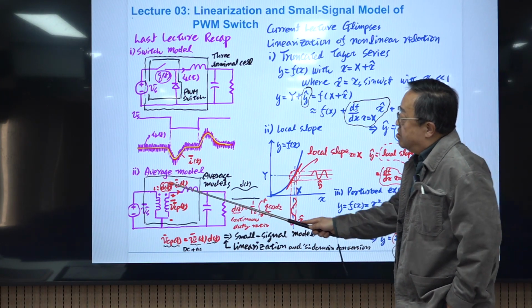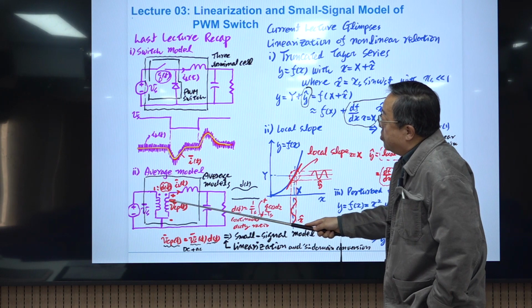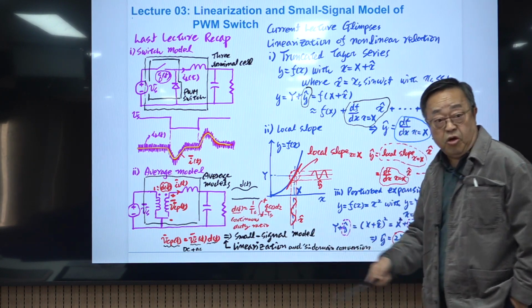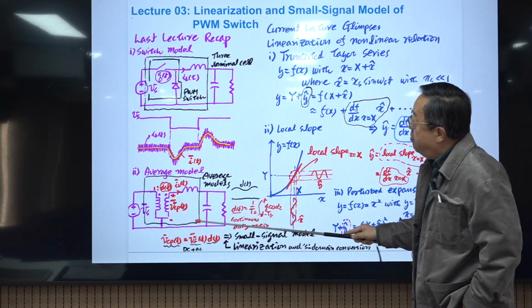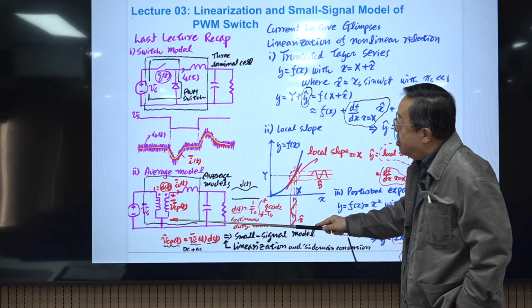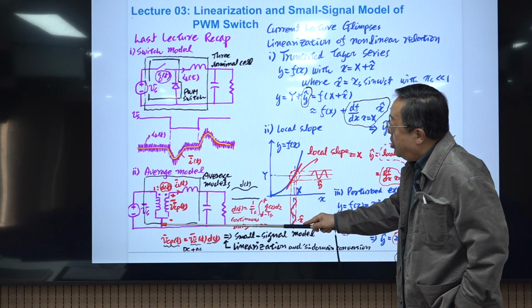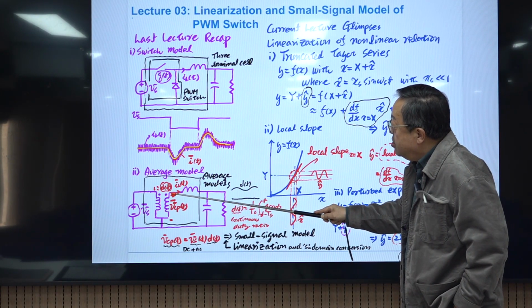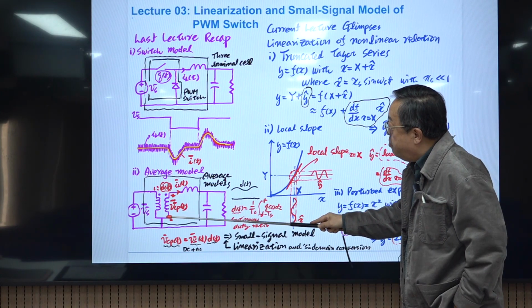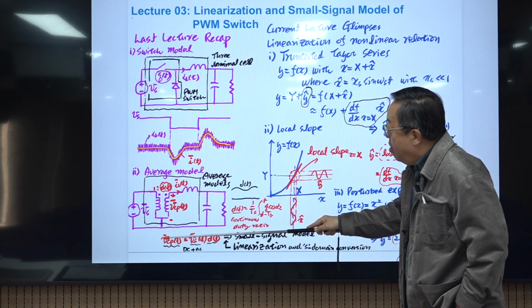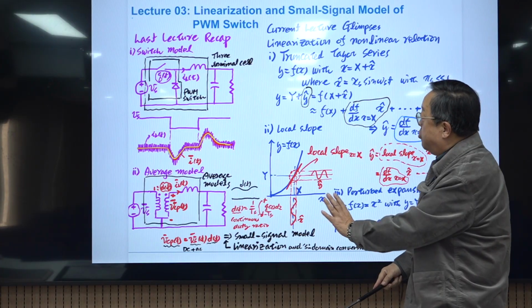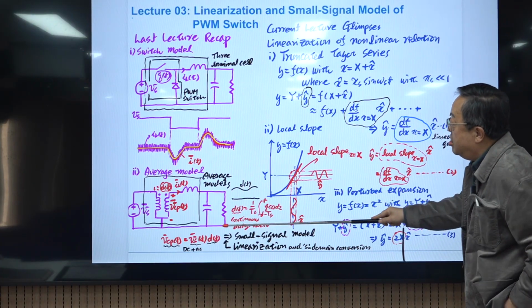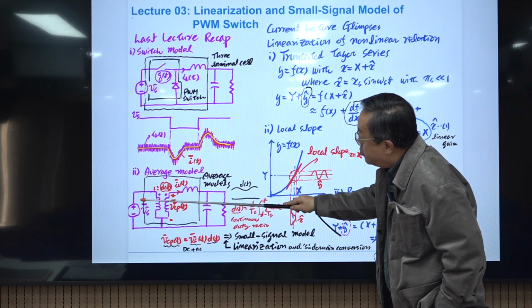So this is time invariant, but it is a nonlinear circuit model, because, for example, take the voltage between the common terminal and the P terminal, v_CP bar, where the bar means the average variable. Something similar to this is a product of variables.